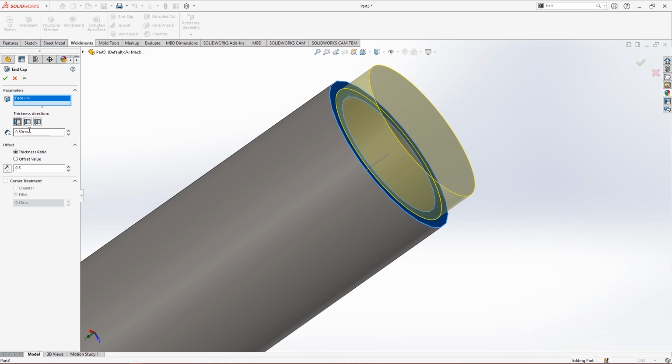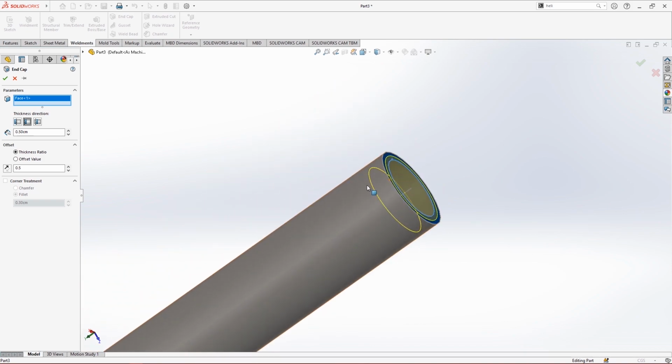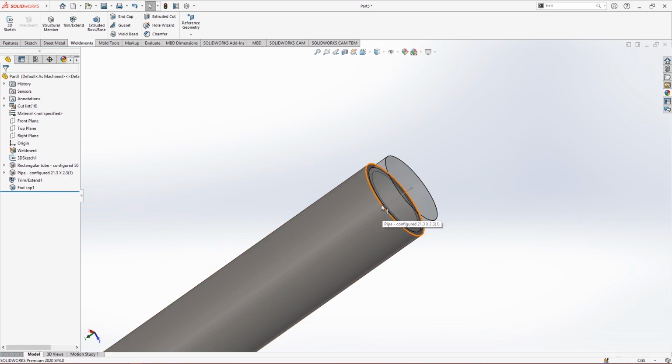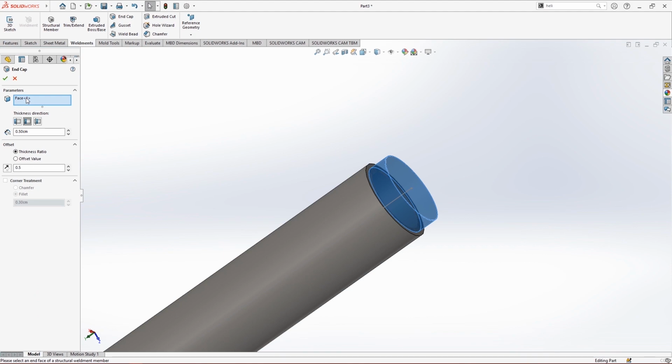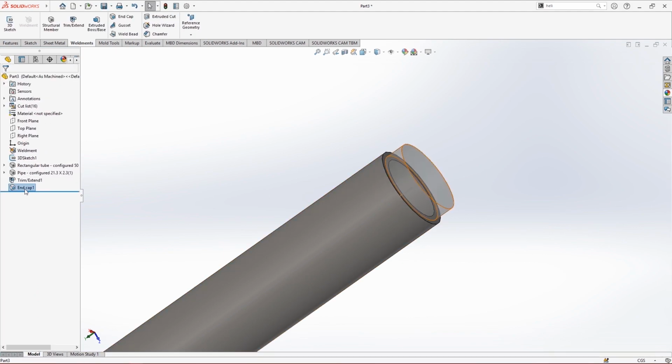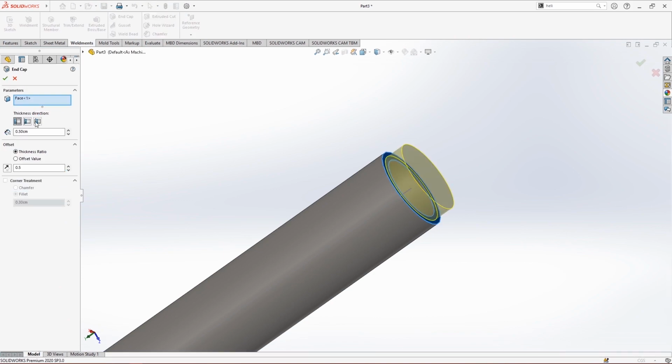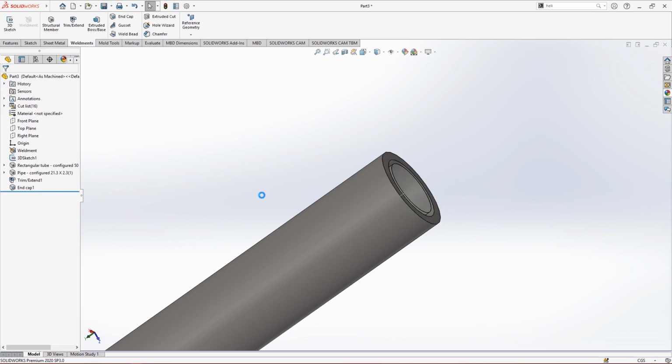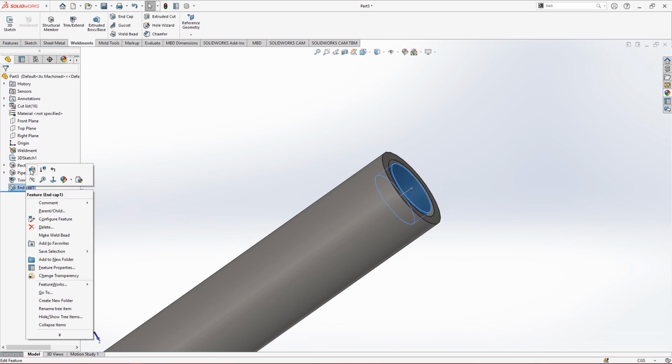But if I keep it internal, then this whole section of pipe will be deleted. For example, you can see the plate and the pipe length is cut, and extra length of end cap is added. But if I choose external, it just stays that way, and I can also use the version where it stays in the center. Now there are a few more properties.